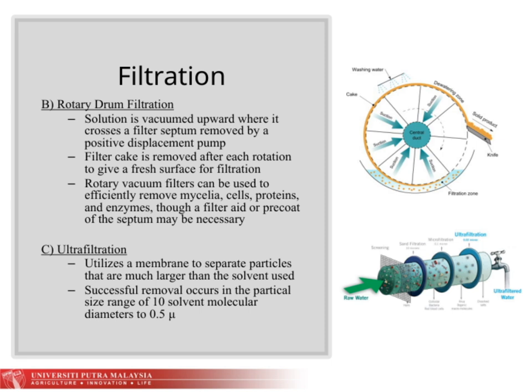Moving on to ultrafiltration, this technique uses a membrane to separate particles based on size. Essentially, it targets particles that are much larger than the solvent molecules. The successful removal typically occurs within the size range of about 10 solvent molecular diameters up to 0.5 micrometers. This makes ultrafiltration particularly useful when you need to isolate or concentrate larger molecules or particles from a solution, fitting into the broader context of our filtration strategies.